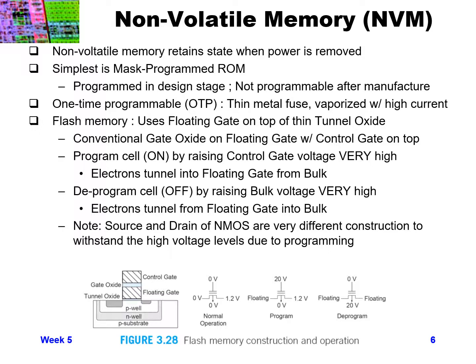So it's something where you program it to a certain value, you always want it to be that value. But from one design, if you find there's a problem, you can quickly change maybe a single metal mask, and start producing new chips in the fab that you reprogram just through changing one single metal device in your mask early on in the process step.